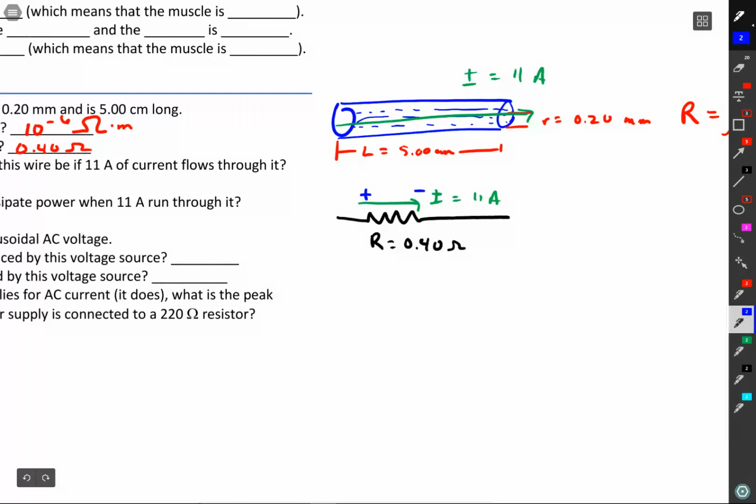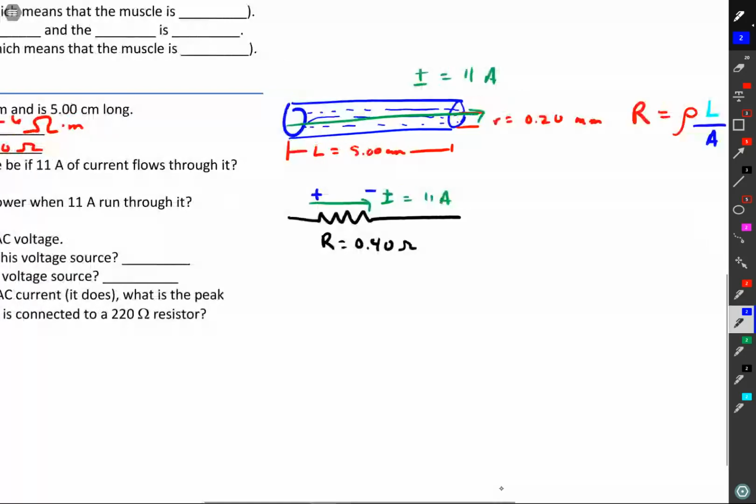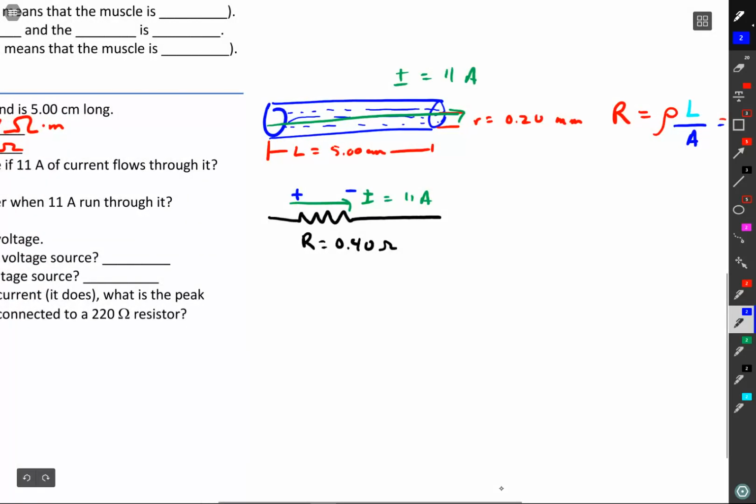Once I have indicated the direction of my current, I can put the positive side and the negative side, because a resistor resists charge going through. It's going to put a force, if you will, against the charge and thus take away energy when charge goes through it. So the energy drops, the voltage is the potential energy per charge, so the potential energy drops as it goes through, hence positive voltage on the side it started, lower voltage on the side it ended. And Ohm's law has the simple relationship. Voltage difference across the resistor is equal to the current through the resistor times resistance.